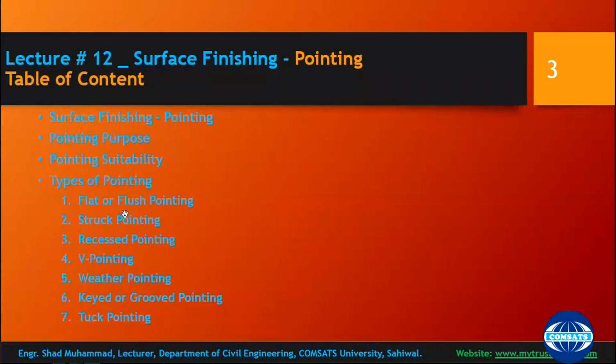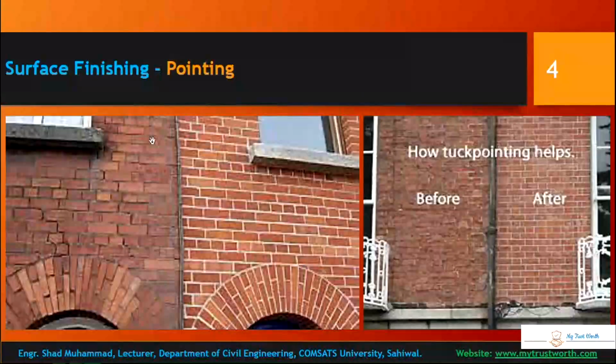We will study flat or flush pointing, struck pointing, recessed pointing, V pointing, weather pointing, keyed or grooved pointing, and tuck pointing. Let me clarify the situation: pointings are based on the type of design which they make. They are not based on material, they are based on the type of design which is finally created. Okay, surface finishing, pointing.